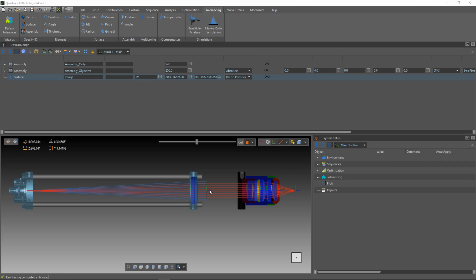In the next step, after aligning the collimator assembly, the objective lens is mounted in front of the collimator. The positioning of the lens also has some tolerances, and only the defocus will be adjusted manually, which is the second step of the alignment strategy. So we have two steps. The first step is the alignment of the collimation, and for the second step, the alignment of the defocus of the objective lens. For this demonstration, we will also ignore the single tolerances inside this assembly of single elements.